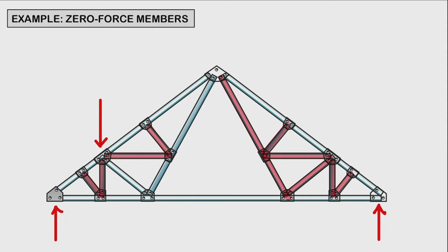Okay. So let's highlight all the members that have forces. So if you're going to examine the different joints on the top chord, these members are actually going to have the same loadings, just like here, same loadings. And on the bottom chord, these are going to have the same loadings. And then these members are also going to be carrying loads.